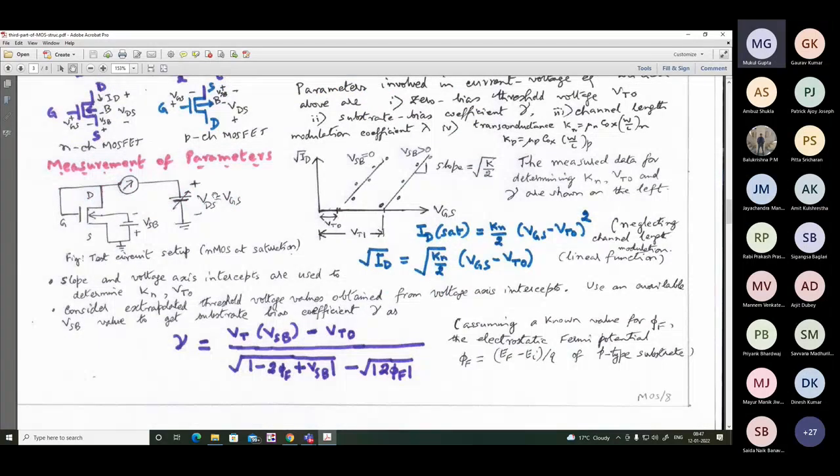All of you can see this experimental setup. If you connect G and D together, you cannot make the transistor go into deep saturation. However high you make the drain to source voltage, the difference between VDS and VGS is only VT, right? All of you note, right? Because VDS and VGS are equal. So what is the difference? That means VDS is greater than VGS minus VT.